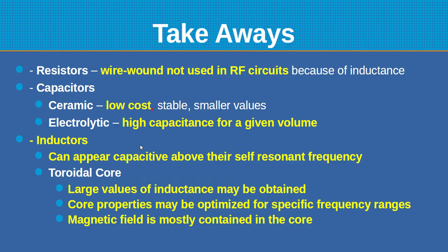But remember that inductors can turn into a capacitor, basically, if you operate them at a frequency above their self-resonant frequency.